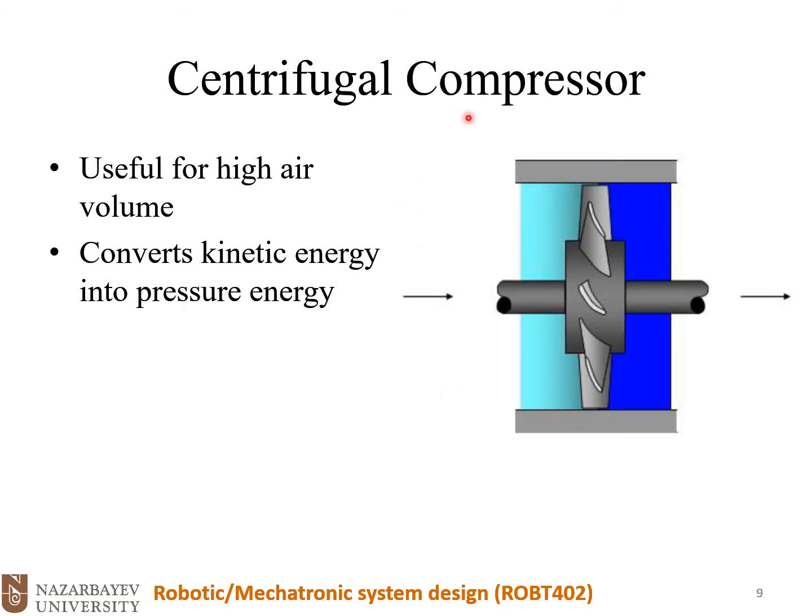The centrifugal compressor basically belongs to the branch of dynamic compressors. It's useful for high air volume, and it converts kinetic energy into pressure energy.